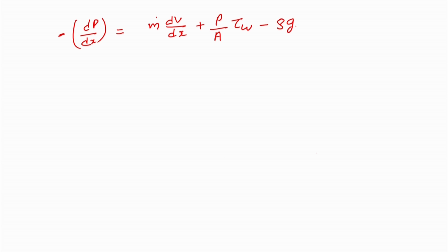If you are writing in one direction, it can be Gx, I can write rho G, and plus and minus just shows the direction of gravity. So what we have said is that dp by dx for single phase flow can be reduced into three parts. One is the acceleration term, delta P due to acceleration, another is the frictional or viscous term, friction, and then the gravity term.